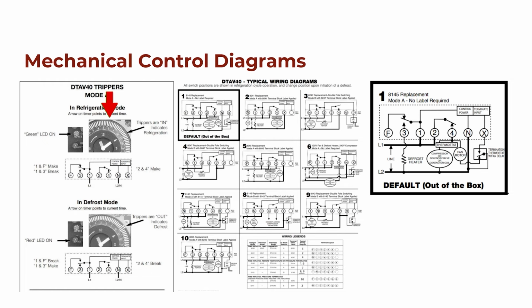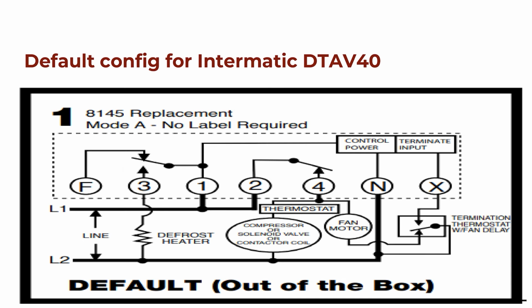Okay, so the sequence of how this is going to work. This timer, we've set the time. It hits at a certain time of day. We know we want the defrost cycle time to be, let's just say 12 o'clock. At 12 o'clock, we want defrost to run for 1 hour. So this is going to hit its set point for defrost. When that happens, these time clock contacts are going to change position, right? This is going to open, and then this contact is going to close.